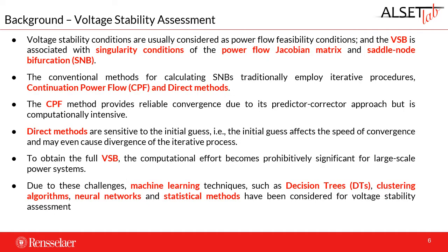Now, voltage stability assessment is a systematic methodology to determine if the system will be stable under different types of contingencies and conditions. Usually we consider the power flow feasibility conditions and the voltage stability boundary associated with singularity conditions of the power flow Jacobian matrix and the Saddle-Node Bifurcation. The conventional methods used are the continuation power flow and direct methods.